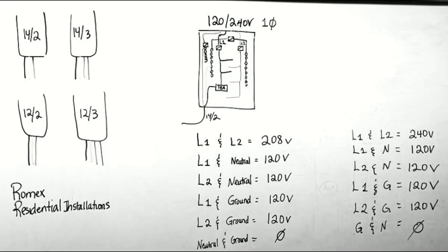So if my current comes through here and it wants to come back to the power source, it can make a complete circle right here, come back to the power source. At this point, it could do the same thing here. It could travel through here and come back to the power source here. So if one of these were to fail, my current still has 9 other paths to come back to the power source. So that's why if you have 10 lights in your house, all of them are wired in parallel. So whenever one of the light bulbs burns, none of the other ones are affected. You just need to find the one that's burned and change it, and that's it, right?